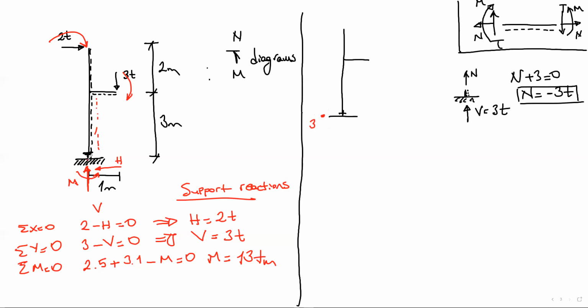So from this point to this point, the cantilever connection point, there is no axial load change. So till this point, it's going to be the same. Negative or positive? Negative. Because we have just calculated here. So put a minus sign over here.